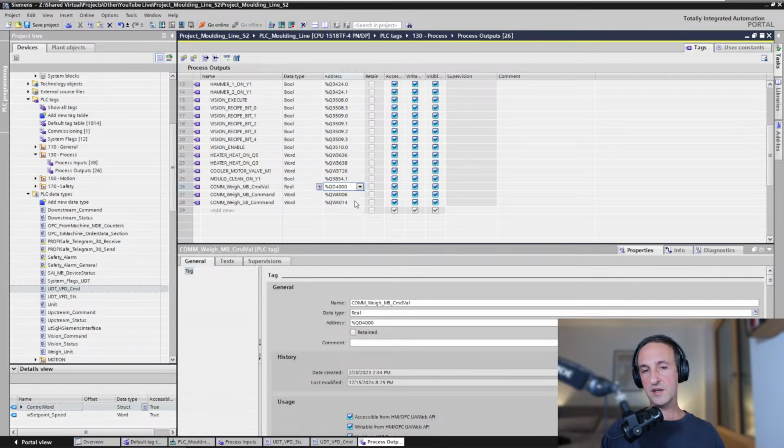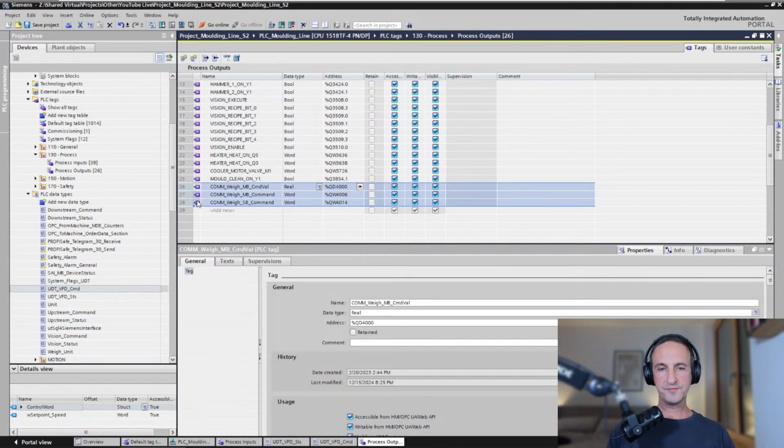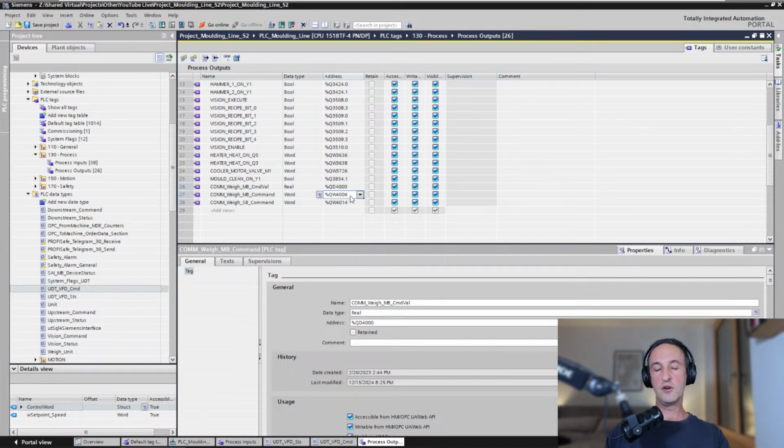You see we have a communication with 3 different tags. So all of these 3 weighing tags, outputs, you could just pour into an output structure, and then you can replace these 3 lines with just one single line. And what's the good thing about this is that there's less chance of errors. If you have more VFDs, you just copy paste one and point to the start address. You don't have to type in 3 different addresses, you just have to type in one address.